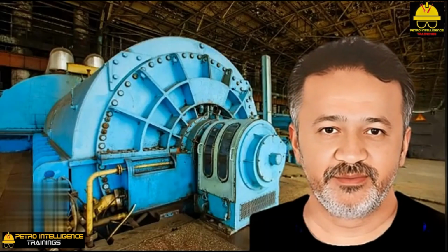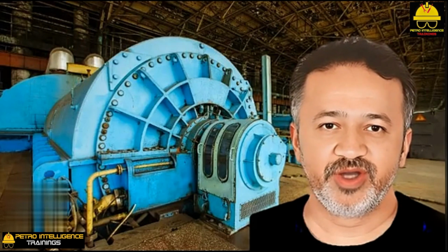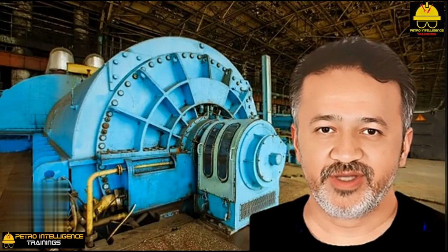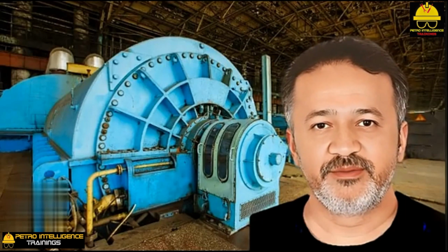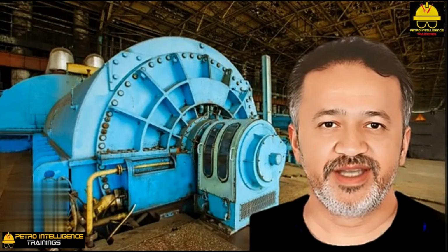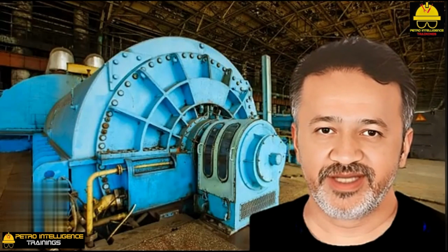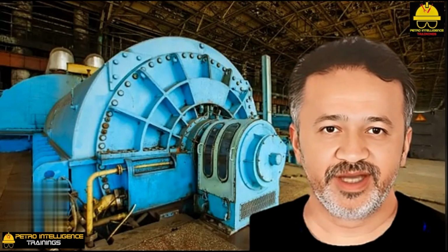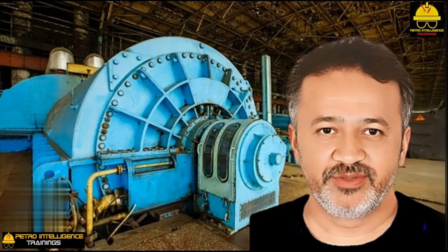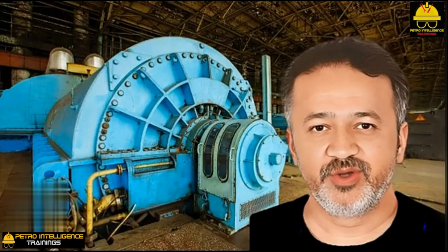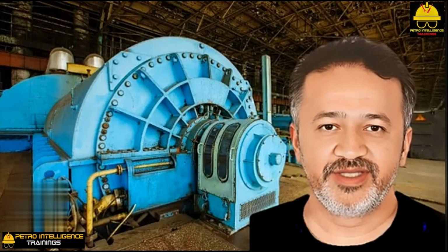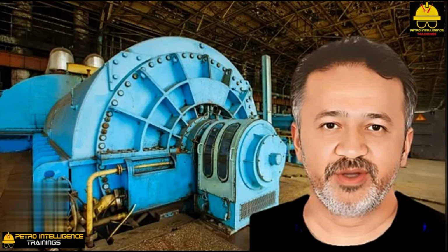Condensing turbines. Most of the turbines you will encounter in your work are called topping, or extraction, turbines. The idea of such a turbine is to extract much of the potential work from the motive steam, and then use the exhaust steam to reboil towers. Typically, the energy content of the exhaust steam is only 10 to 20% less than that of the motive steam. That is the calculation we just did with the Mollier diagram. The rest of the energy of the steam may then be used as the steam condenses to reboil towers. This sounds pretty efficient. It is the basis for the new cogeneration projects you may have heard about.